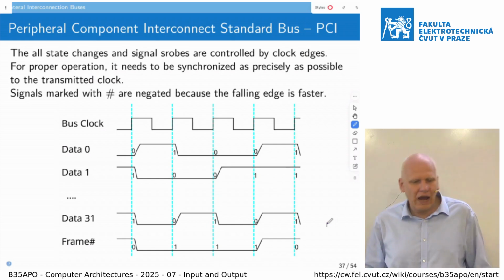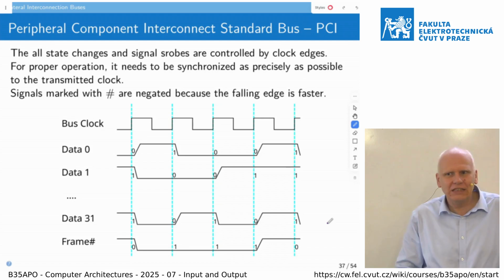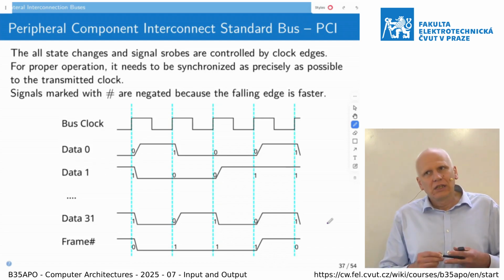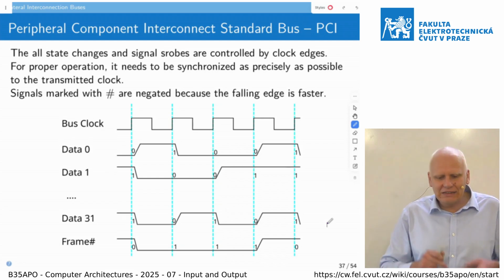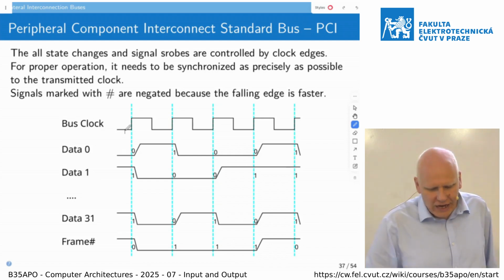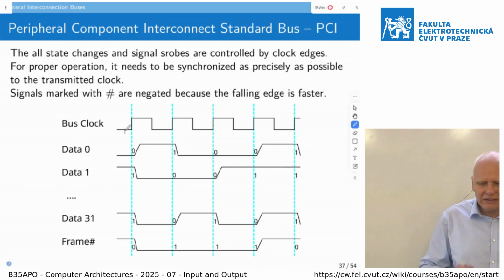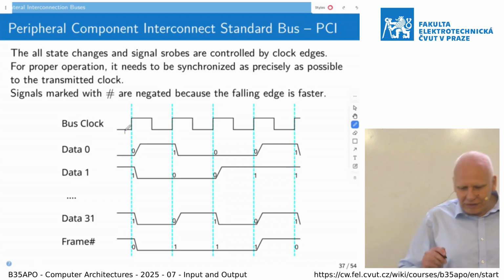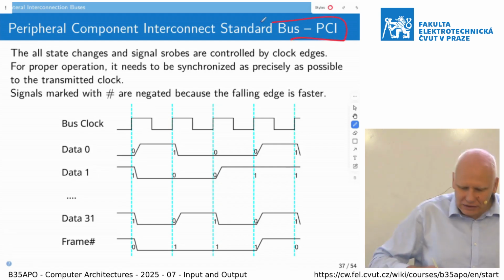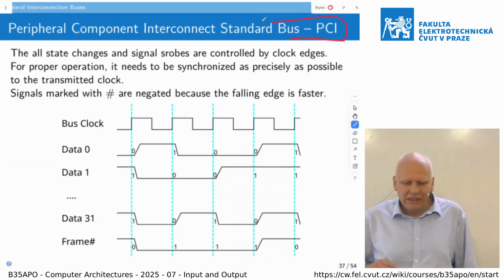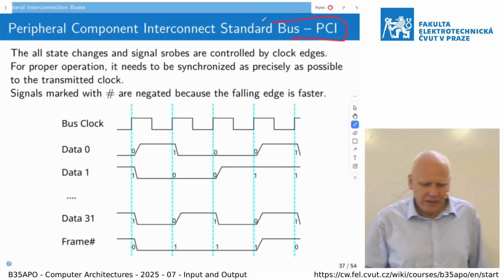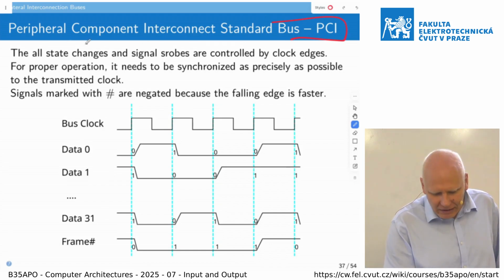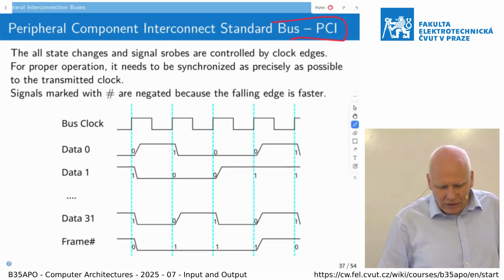And if we look now a little back to the PCI, so PCI is not important today for the other interconnection bus in the PCs. But internally inside the chip, those mechanisms which I describe here on the PCI bus are still often used. And because the PCI bus is an older bus, it is still relatively simple to describe it. So we start with that PCI bus, and the mechanism even on the PCI Express is compatible with the PCI. So what is the PCI, the peripheral component interconnect bus?